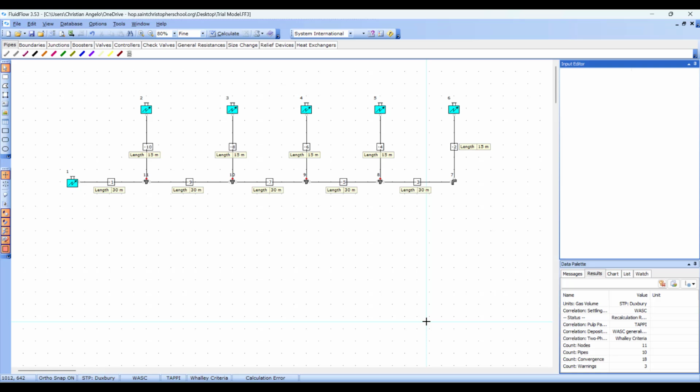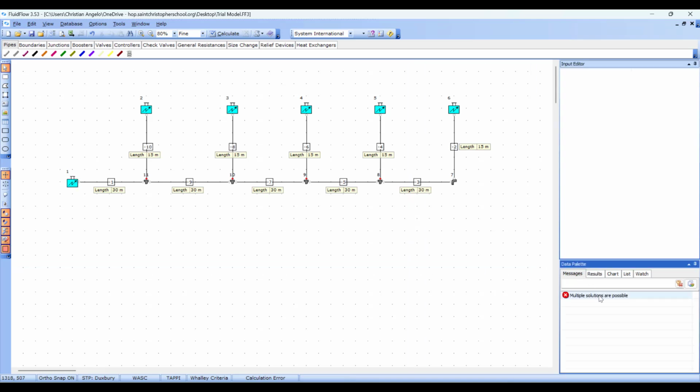Now, when we hit Calculate, the solver will try to force the specified flow to occur on each of the components. However, in its current state, the model is overconstrained, as we have specified flow throughout the system, but pressure is not specified at any point in the model. As discussed in the previous sessions, at least one pressure node, either as a known pressure or a reservoir component, is needed for the solver as a reference in initiating the calculations. Thus, in the case of our current model, the solver cannot provide a correct result. Hence, it encounters a calculation error.